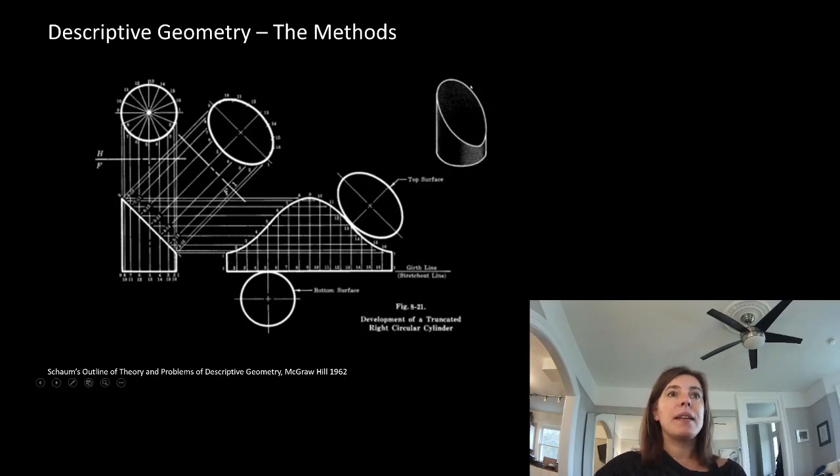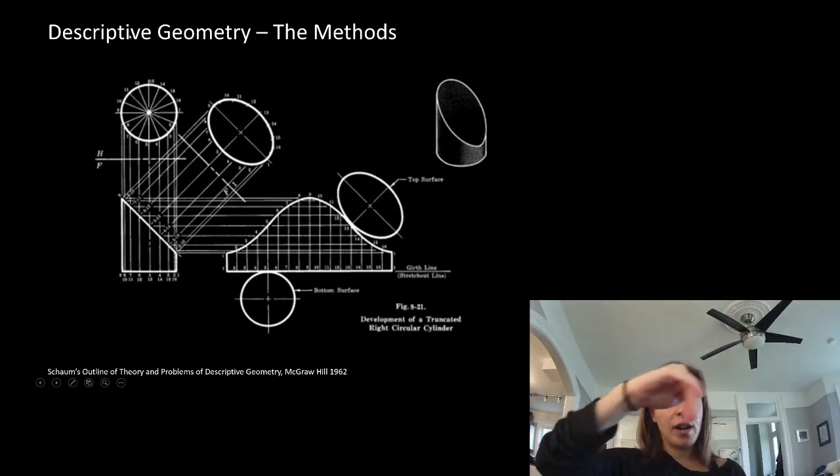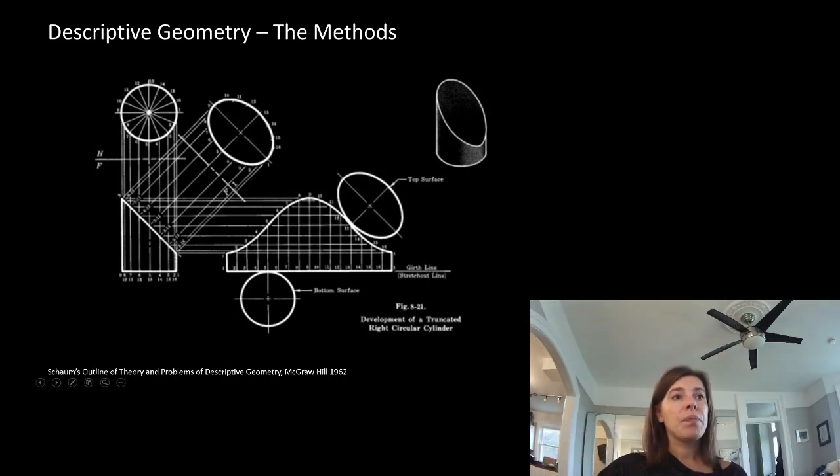So you can see it makes an ellipse here, that's represented by this drawing here. In plan, looking straight down on it, it would be represented as a circle. And here is a rolled out elevation of the surface. So it would take all of these for somebody to actually create this object. If you needed to give them information in 2D so that they could produce this product, this is how they would need to describe it.